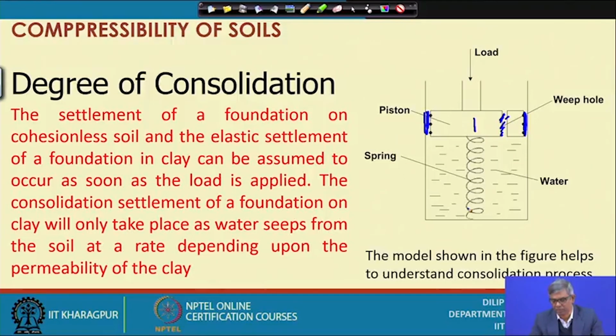and because of that, the water will be pressurized. That means pressure will develop within the water. If I apply some amount of load P, an equal pressure will be developed within the water, but still there is no transfer of load to the spring.